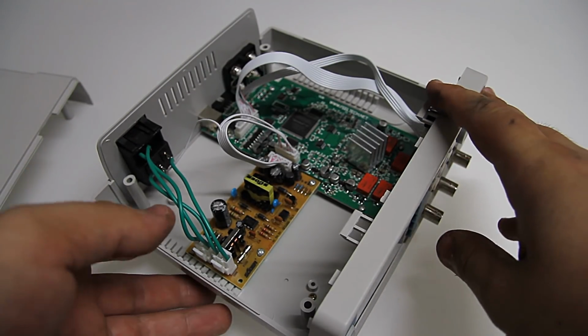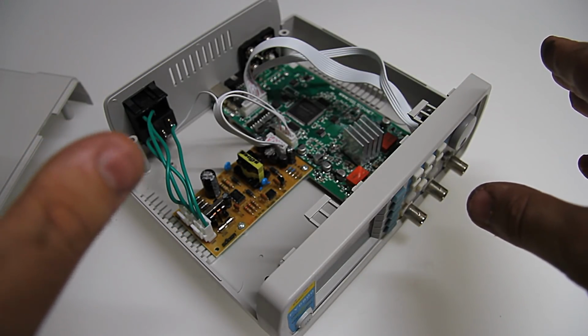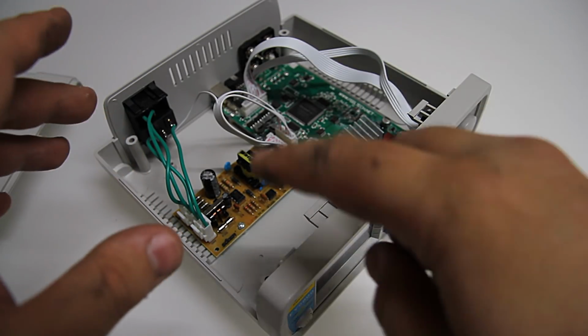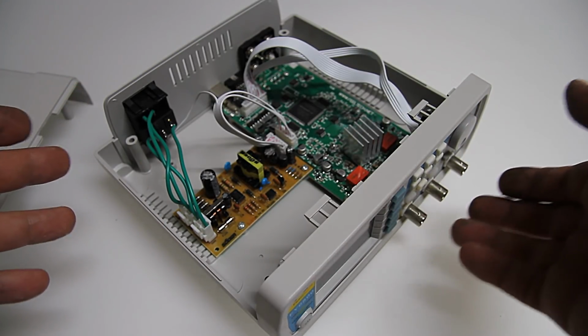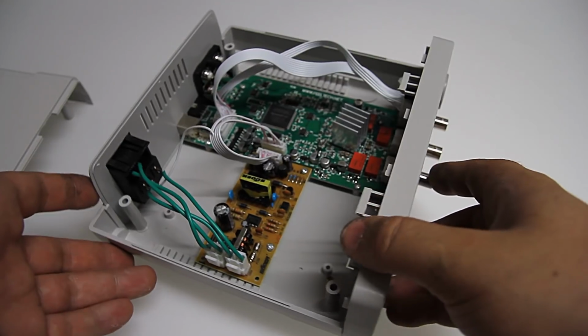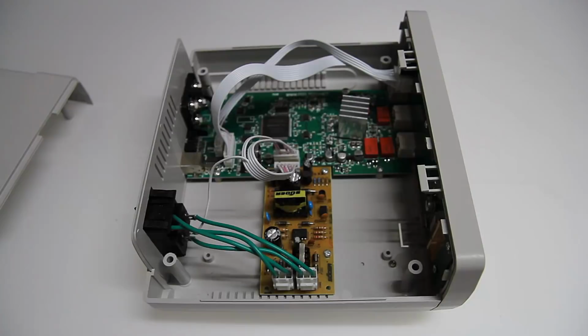Some users of the previous model mentioned a potential of about 60 volts leakage through this device from the mains to the BNC connectors, and if they are grounded, there should be no potential, except if the cable is broken or if your wall socket isn't grounded.